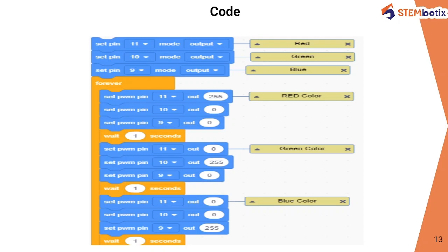Let's talk about the reverse current. Let's imagine that our RGB LED is connected to 5 volts. For the red, green, and blue colors, the reverse current remains the same, which is 10 microamperes. Let's talk about the illumination intensity. For red, the illumination intensity is 800 MCD.